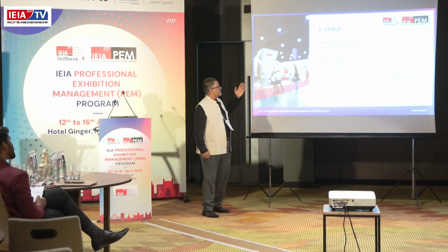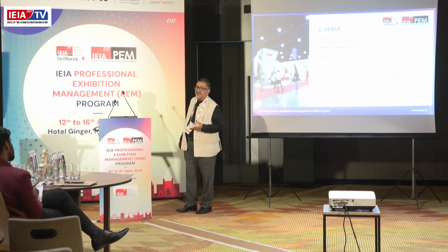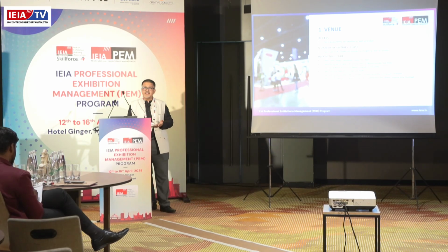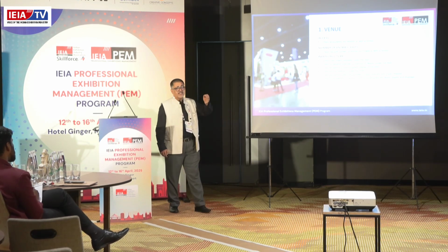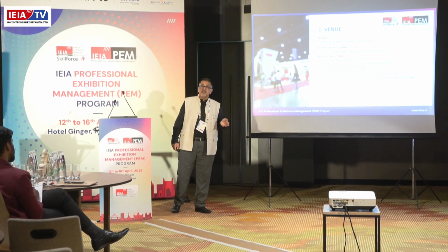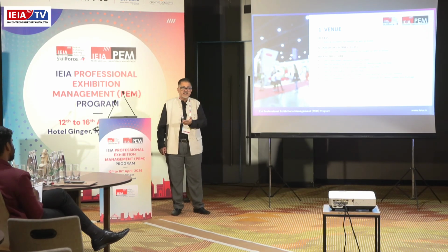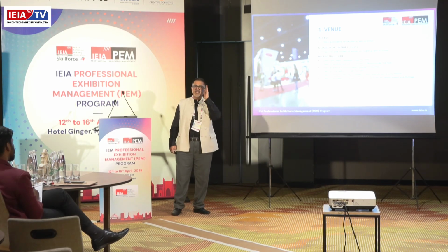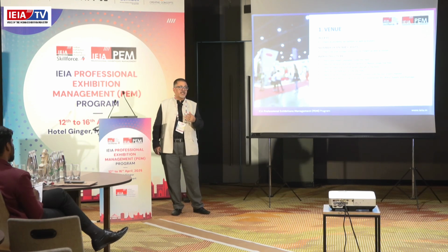So it's important to also check where the electrical panels are placed, where the fire hydrants are placed, where the fire exits are, and as Surajji just mentioned, fire curtains. In Bharat Mandapam, the old halls had no fire curtains and still have none, but all the new halls have fire curtains. So you have to make sure that the fire curtain space is left free of any obstruction at all times.